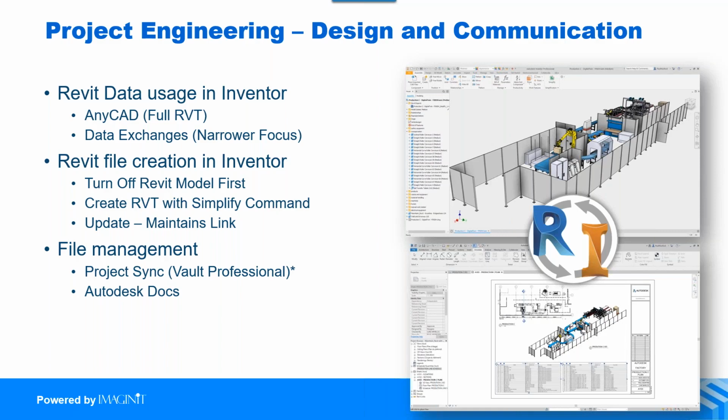Now for file management, again, there's kind of two ways to do this, depending what kind of world you live in and how you like to track your data. First and foremost, there is a project sync functionality inside of Vault Professional that allows me to take files that are in my Vault and synchronize them to the construction cloud, to the Autodesk Docs system, or I could just use Autodesk Docs directly. So what's really different here is the use of Autodesk Docs, it's always going to stay in sync. Things are always going to be synchronizing back and forth.